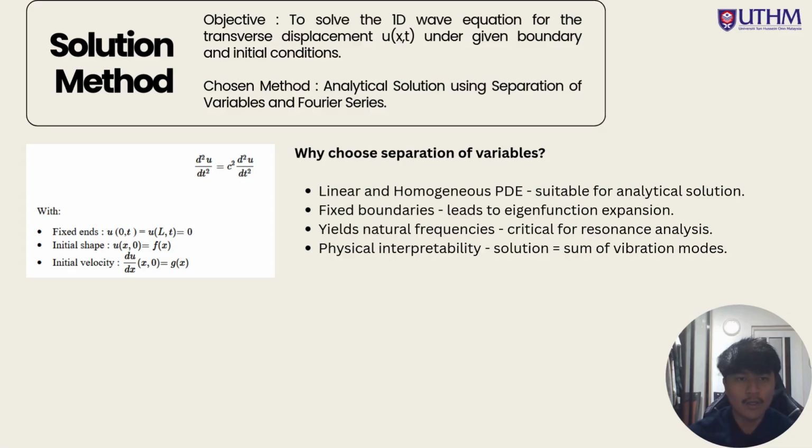And then why did we choose separation of variables? Firstly, because it is a linear and homogeneous PDE, which is suitable for analytical solution, and it has fixed boundaries, which leads to eigenfunction expansion. This method yields an exact analytical solution in the form of an infinite series, which is physically interpretable as a superposition of vibration modes. Analytical solutions also allow for clear parametric studies and natural frequency extraction, which is essential for resonance analysis.